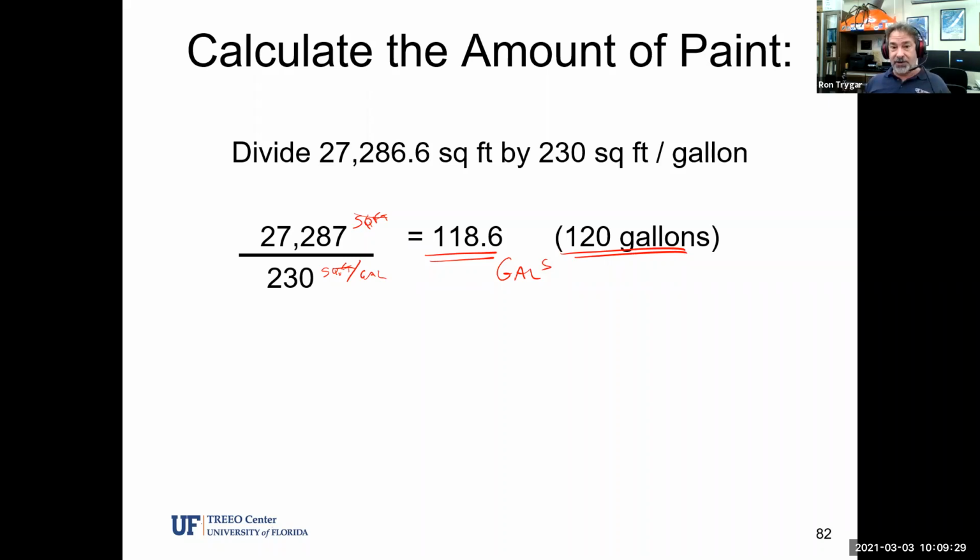If it's the exterior and it's just the outside part and the ceiling, or rather the roof, then you only have one circular shape to calculate, is the top, the ceiling or the roof rather. And then the middle section, which is the wall. So pretty straightforward, but a lot of steps. Remember, this may take you a little bit of a while to do, so take your time with it and practice. Use these examples to practice with. If you know what the dimensions are of your storage tanks, plug your numbers in instead of using the numbers I gave you. Plug your numbers in and work the math out.